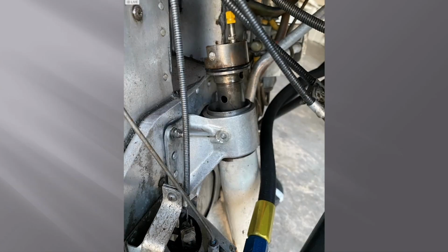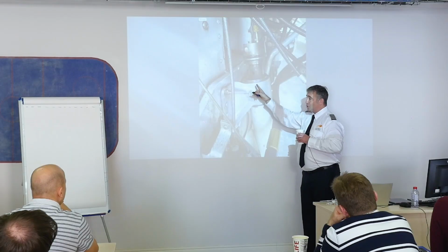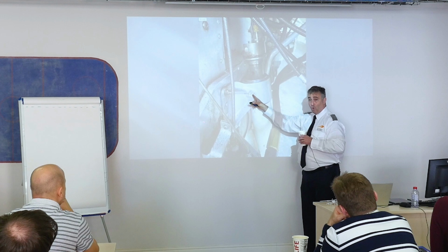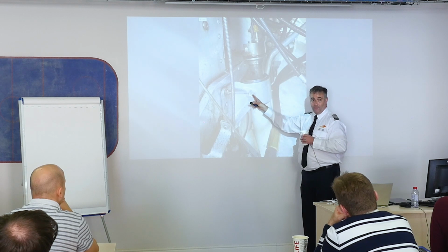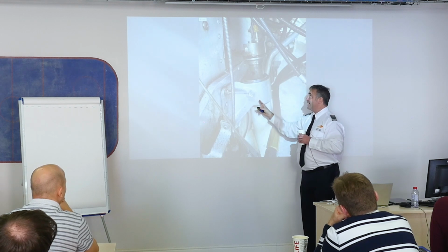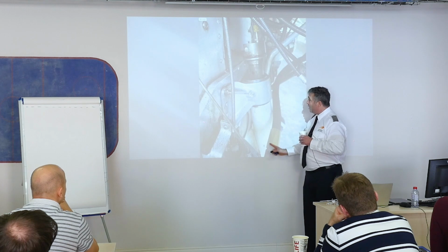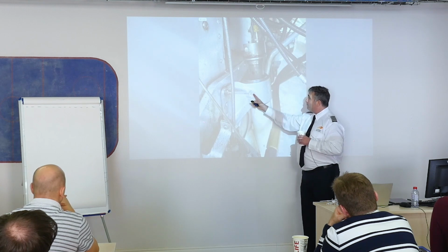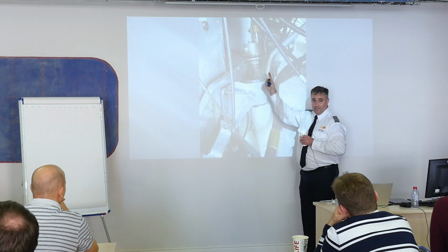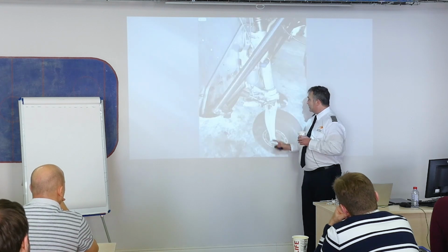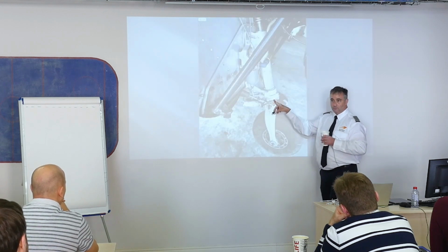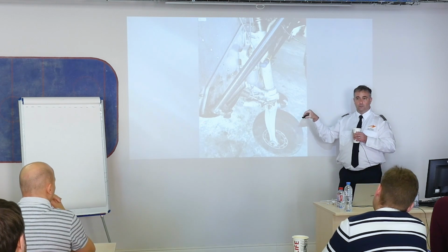But, whoa! This is the cylinder. The strut goes into there. That's a bolt that should go through this hole. Somebody landed this airplane very hard and broke the bolt in the entire strut. And you can see, like you said, there's nothing here. No strut here at all.